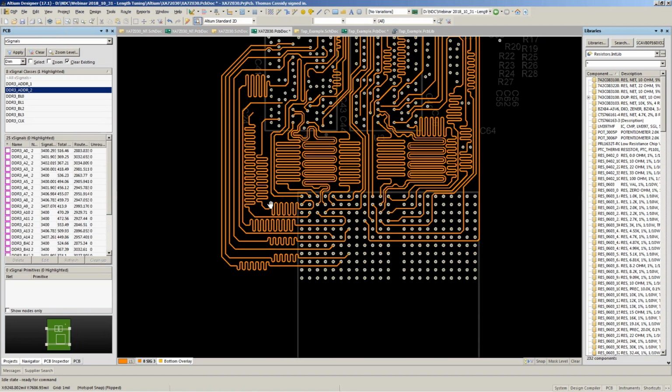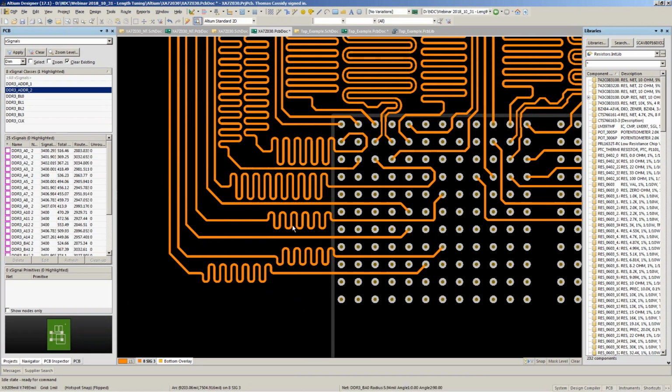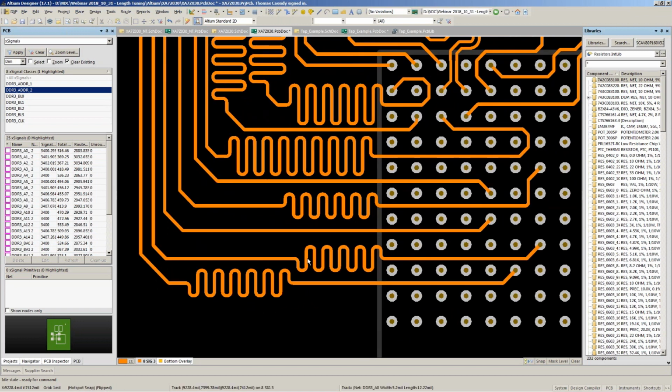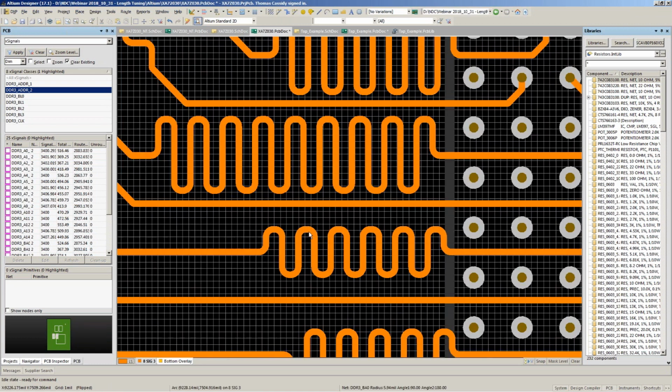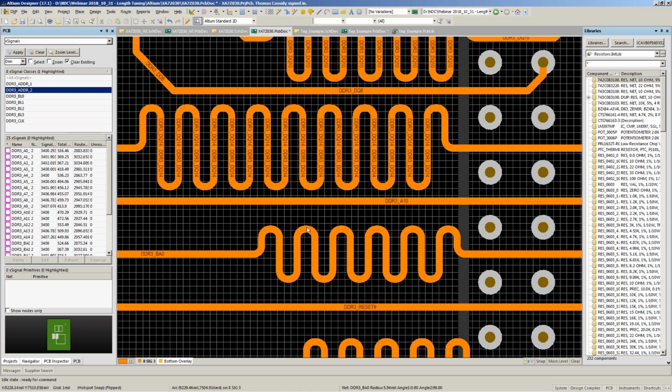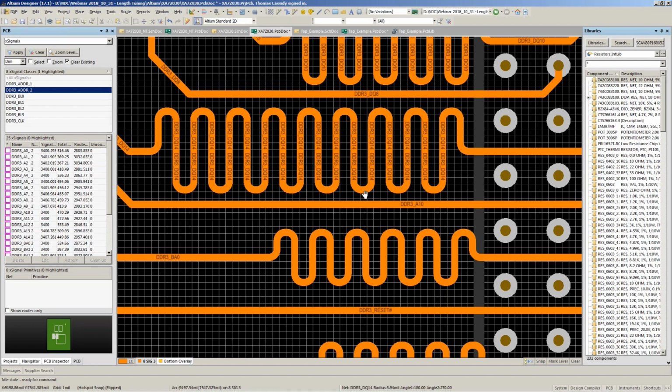So I just want to show a couple quick examples of some of the things Paul was talking about, in this very old DDR3 design. I like to use the rounded, as Paul mentioned, and the reason I do that is mainly from a signal integrity point of view. If your routing lets you have a fair amount of space between your traces, it's not that big of a deal, but sometimes you're just going to have to get close. You just can't avoid it. If you're doing that and you've got a rounded signal, the only perfectly parallel point is tangent to that line. You don't have a large area of parallelism, and therefore your crosstalk will be minimized. The downside, of course, is purely rounded arcs are harder to work with.